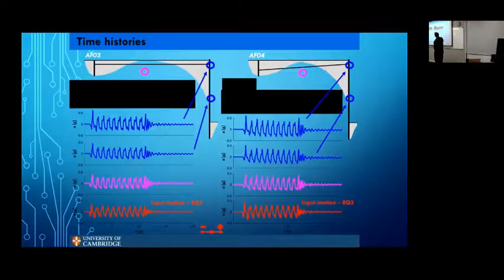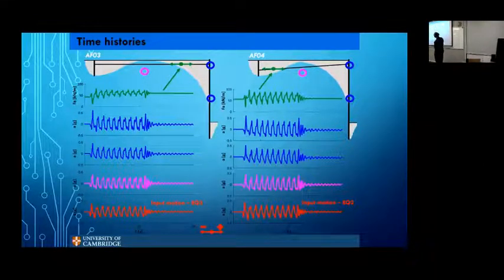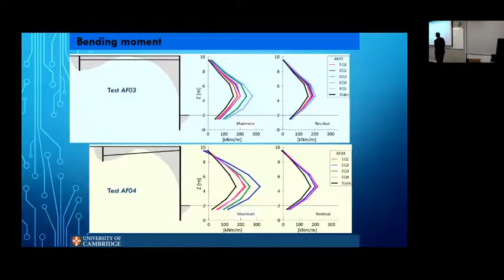Then we can see what's going on in the wall itself, how the accelerations are, and also the forces that are being generated within the anchors as well. So you are getting about 100 kilonewtons in this case, and a bit smaller, but some with residual value there. And that becomes clear a little later.